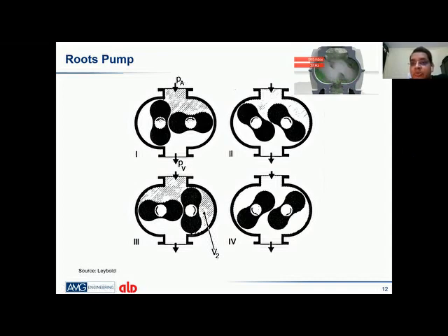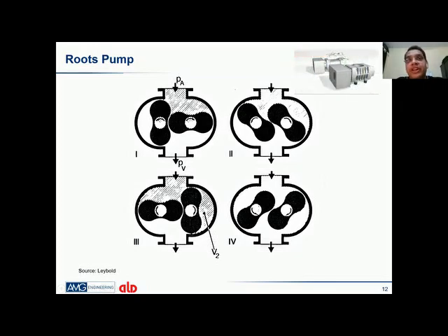Nowadays these roots pumps come with a frequency drive, so you can increase the speed of the rotors up to 100 hertz. When the furnace is very new, we get a very good vacuum level of 10^-4 and 10^-5, but after working some years, because of contamination and atmospheric conditions, we will not get that much vacuum level. These roots pumps usually work at 50 hertz, but now you can start that pump at 70 or 80 hertz to keep your cycle times the same, so the generation of vacuum inside the furnace is the same. Then use this kind of booster pump.